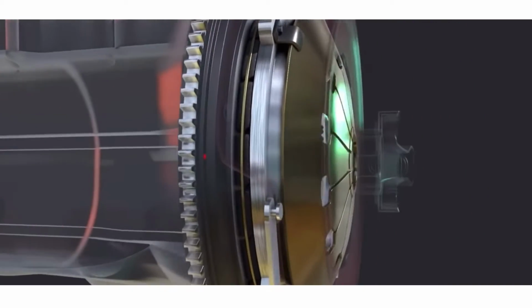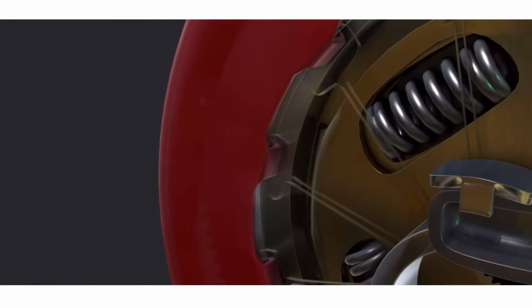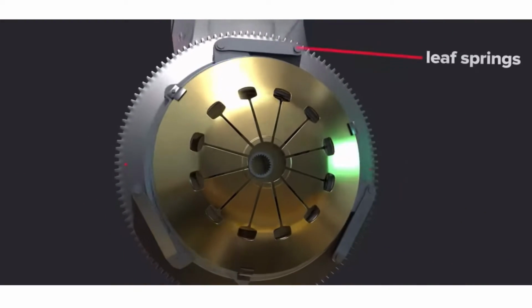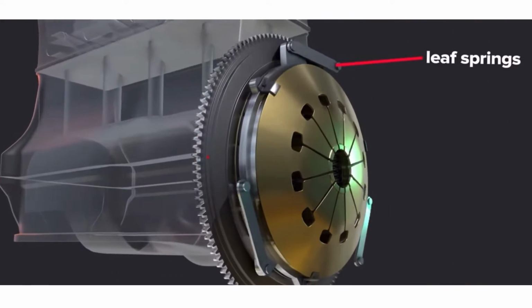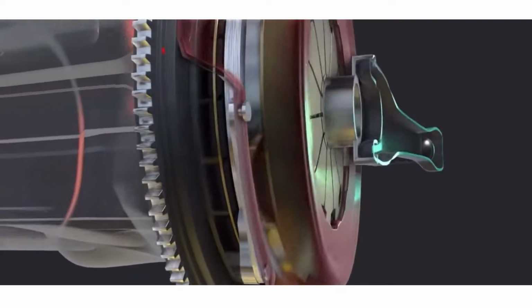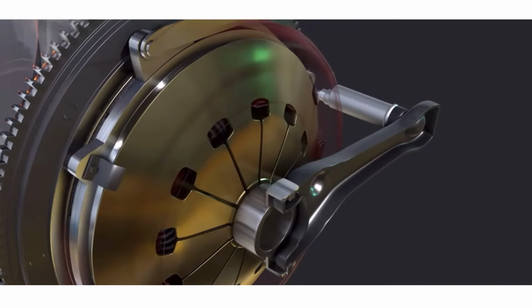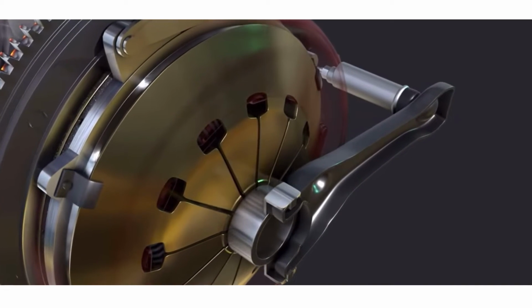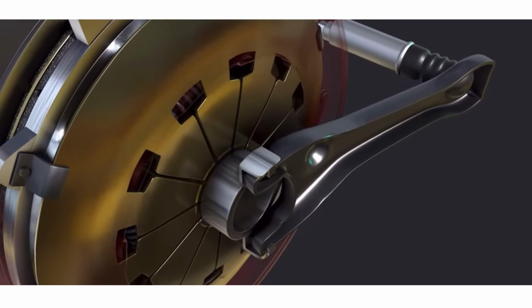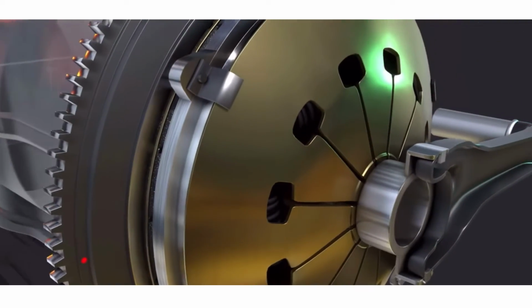7. Shafts. There are usually 3 shafts used in a manual transmission. Those are: 1. Main shaft. It is the shaft that is also called the output shaft and is placed in front of the clutch shaft and in parallel to the lay shaft. Gears, gear lever, along with the meshing devices, such as dog clutches and synchromesh devices, are mounted over this shaft.